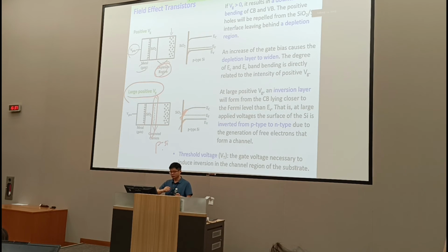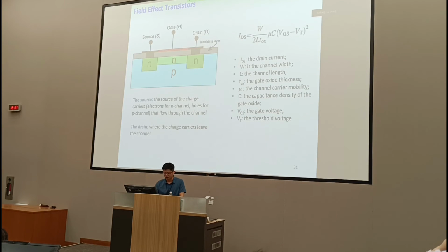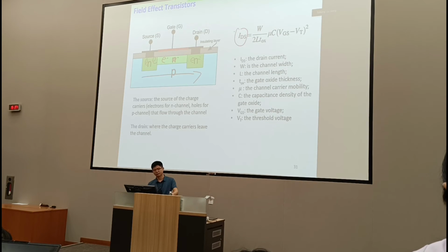On the left, the source and drain have a lot of electrons, right? When you have this inversion layer, you also create electron accumulation inside this channel from the P-type material by gating. You sort of open that channel, which opens the current flow. You have the on state, you create a source-drain current. Okay, you turn on the device, right? Using the gate.